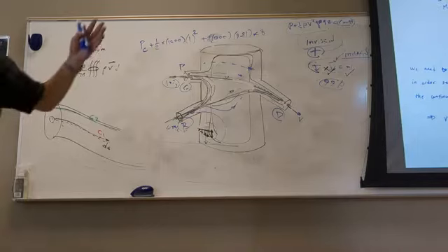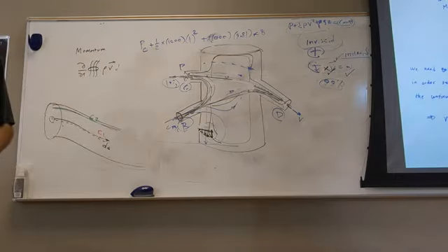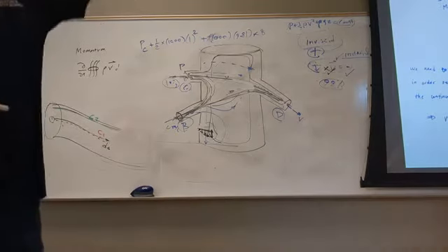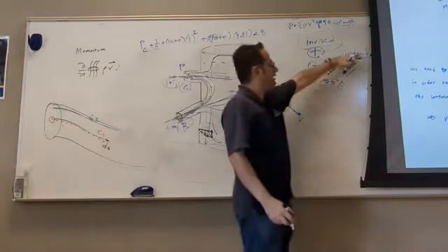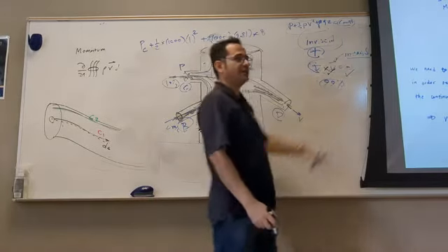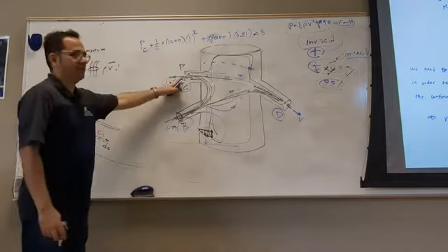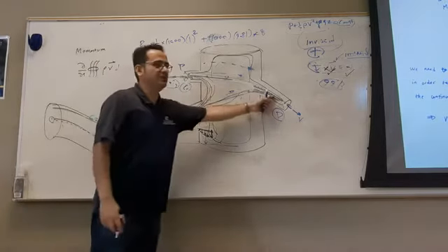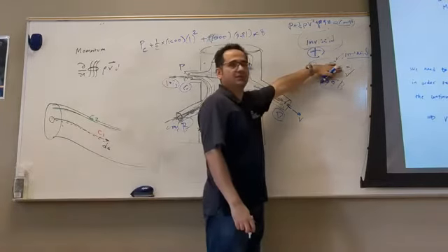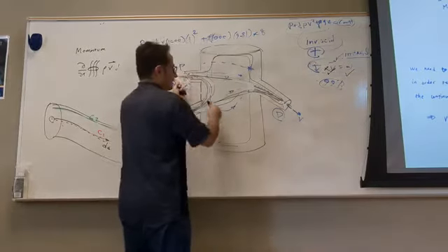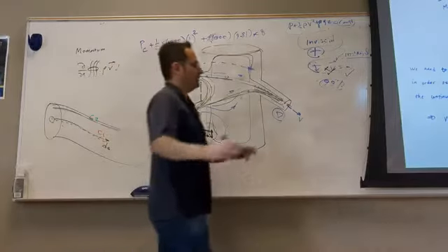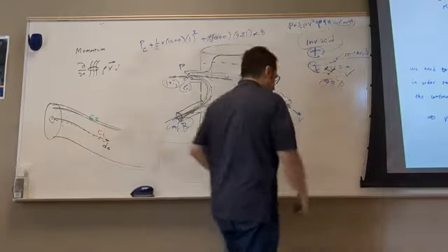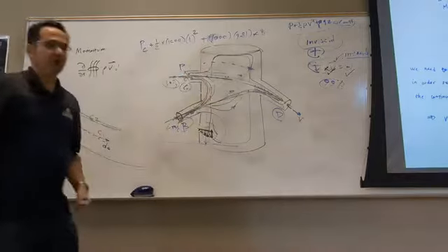This could be a question in the final exam, very conceptual. In the final exam, it's not like just give me those numbers or plug it in here. I may ask, well, I do not make the assumption of irrotational. Solve that, and then you get pressure negative here. And then can you write Bernoulli between these two without this assumption? No. Because this is going this way. There is no streamline between these two. But if we have the assumption of irrotational, yes, we can write Bernoulli between any points.